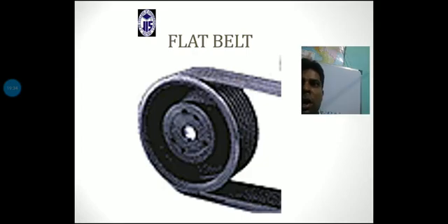That means the belt length will contract, and contraction means a slight reduction of the speed will happen. That reduction of the speed of the driven pulley, and creep, adversely affects the transmission efficiency also. It is also very important to count the different modes of creep. So that is actually the case of creep in belts.